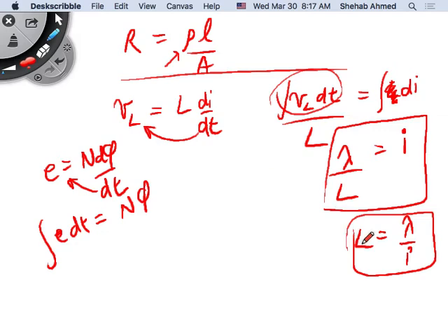inductance is to do what? To find out the inductance of a conductor carrying current I, right? Our objective then is to calculate this flux linkage, because we know the current I that it's carrying. And similarly with capacitance, Vc is equal to, so we need to calculate flux linkage, all the flux linkage linking this specific conductor, right?